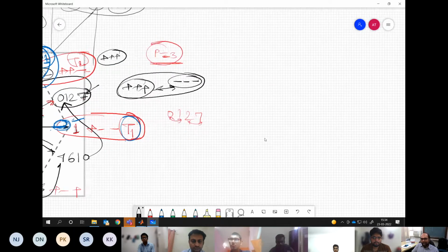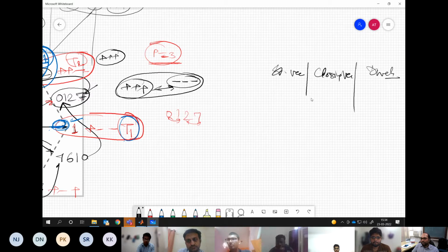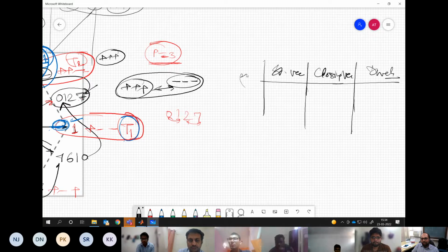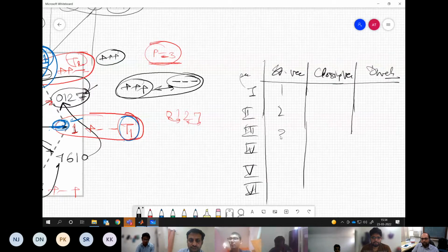Or shall I write starting vector, closing vector, and the dwell time. So starting vector, let's say sector wise we are writing 1, 2, 3, 4, 5, 6. What do we have? We have 1, 2, 3, 4, 5, 6, and the closing vector starts from 2, 3, 4, 5, 6, 1.